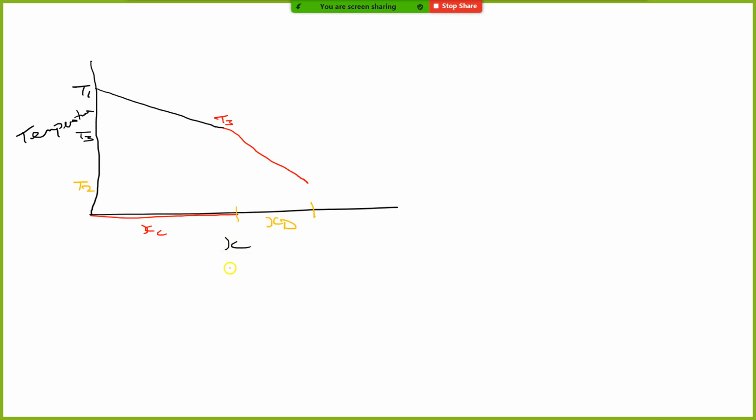Let me know if you guys follow what I'm saying here, because the materials are joined together, you have to connect the temperature difference on the same graph, right? This is how we generally go about it, where you have the first temperature gradient for the first material, and then a final temperature that is met. That final temperature is going to be the initial temperature for the next material, and so you would start the next portion of the graph from there, right?